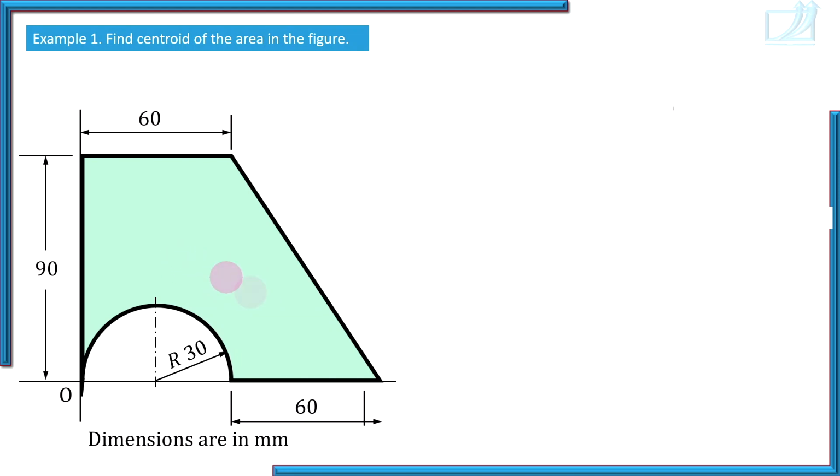If you think there is a hole or slot in that particular shape, then in your imagination fill that slot. So watch here, this semicircular area we have imagined filled, and now the shape you get, you divide it into standard shapes. So it is a rectangle plus triangle. If you add area of rectangle and area of triangle, is it the given shape?